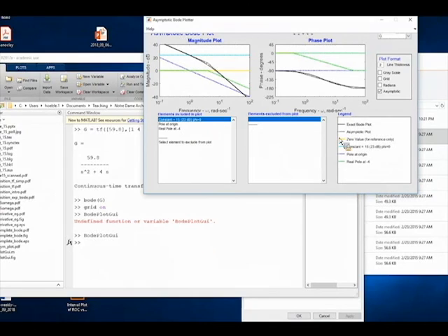I can't seem to zoom in on this, but what you'll see here is it labels everything. So you have a pole at the origin that's given by this blue dotted line, real pole at -4, constant at 15. These are all the elements that we chose to plot in our solution, and you can see these directly reflected on this plot. The thin black line here is the actual Bode plot, the exact one, and you can see it with phase as well.